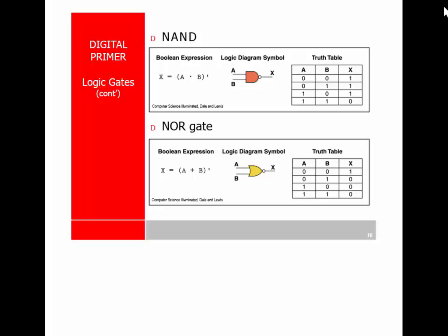But a gate array is a sea of gates put on a piece of silicon. It's 5 million, 10 million NAND gates on one little piece of silicon the size of your fingernail. And then you can connect those up to do any type of function you want. You can build inverters with it. You can do flip-flops. You can do memory devices. You can do everything with that. And there's an entire series of devices out there that are based on gate arrays.